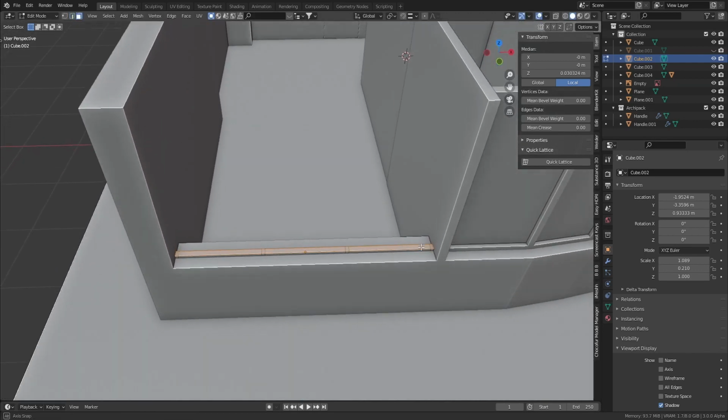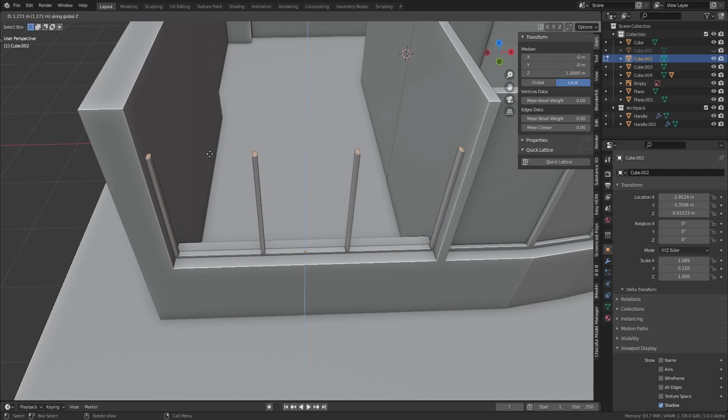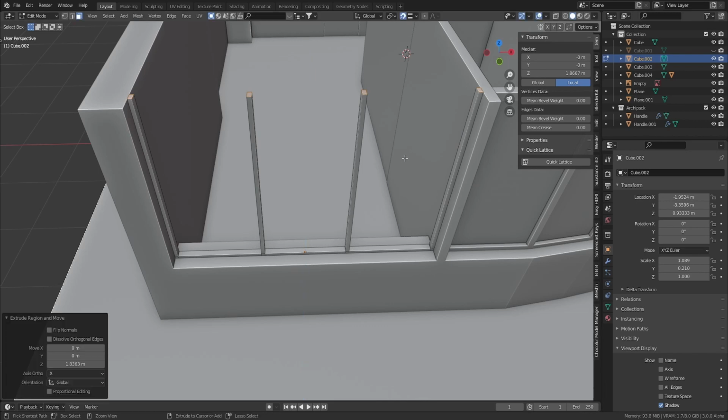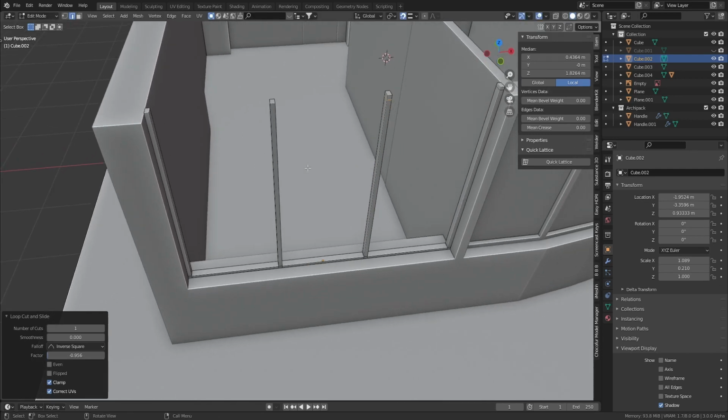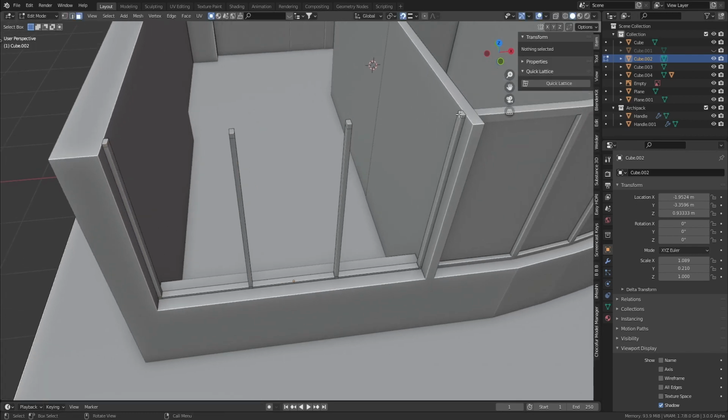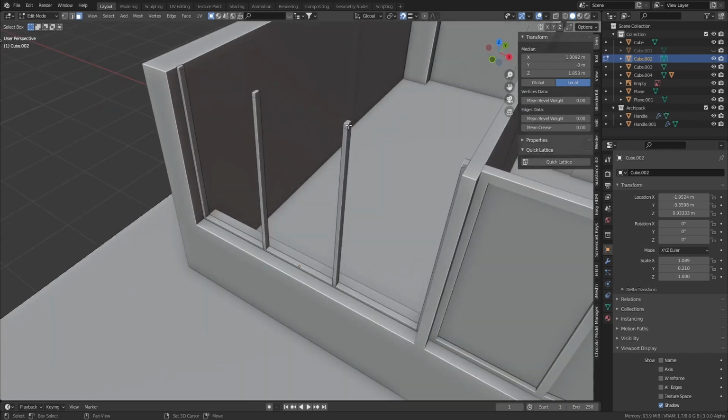Then I need to deselect these faces by clicking Shift and clicking this face. Then extrude these faces to the ceiling by snapping it directly. So don't forget to enable the snap mode. Then I need to create the upper frame for this window by adding extra loops at the top. So like this, add extra loop, then snap it to the previous loop, like this, snap it to the previous loop, then make the same bridge that I did in the previous video.